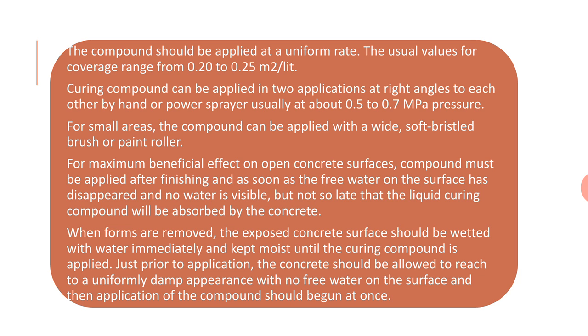When forms are removed, the exposed concrete surface should be wetted with water immediately and kept moist until the curing compound is applied. Just prior to the application, the concrete should be allowed to reach a uniformly damp appearance with no free water on the surface, and then application of curing compound should begin at once.